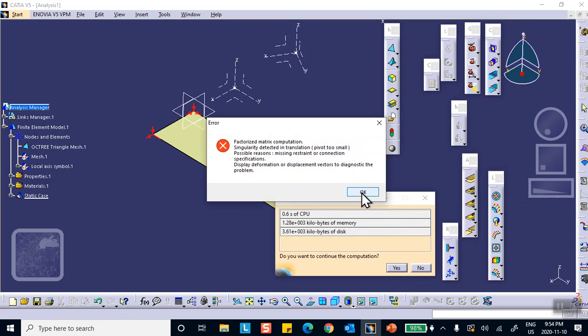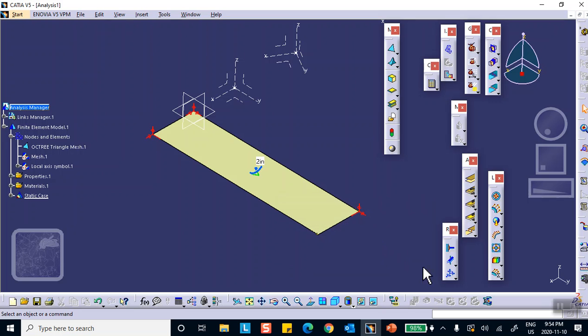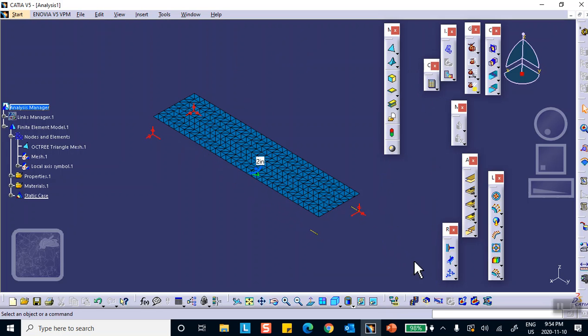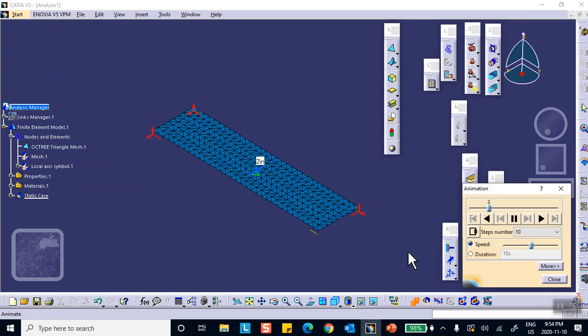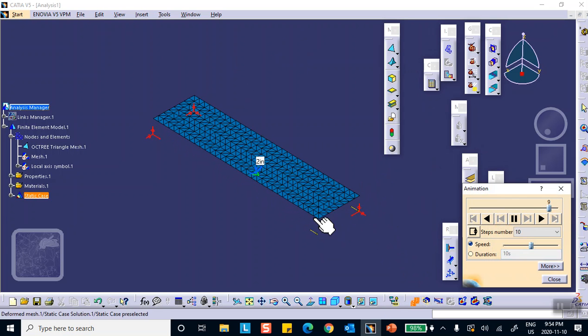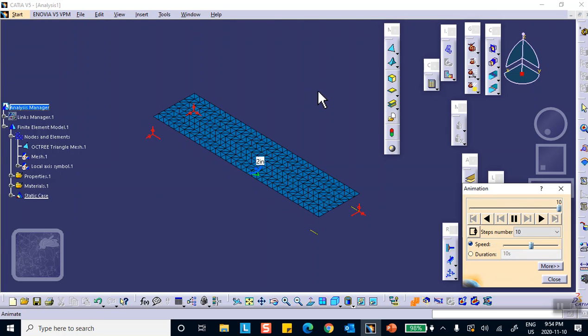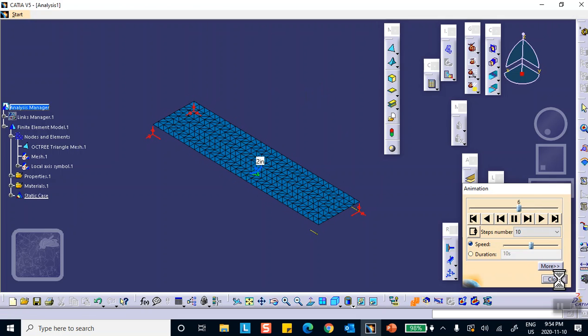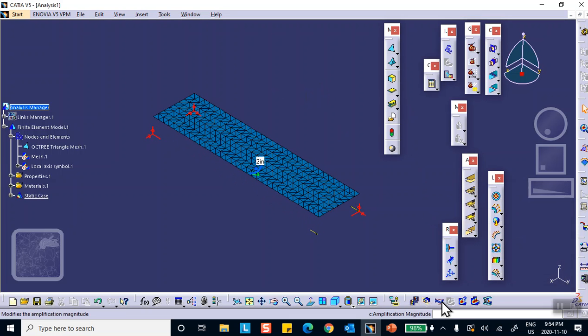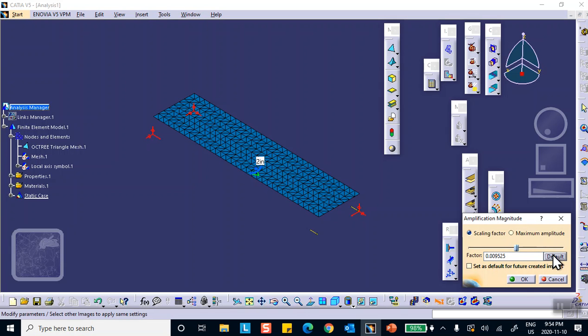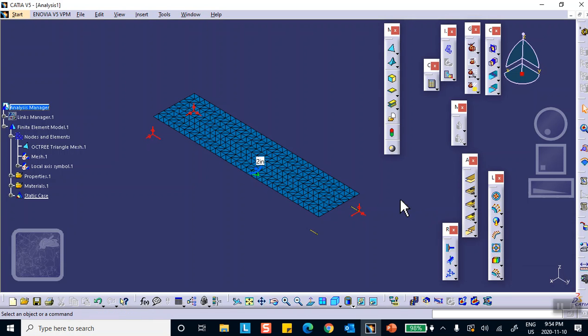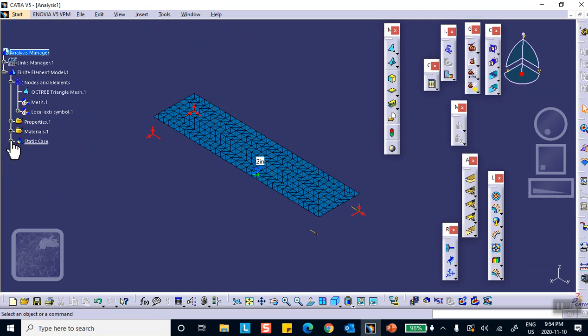There. And the reason, if you want to know what the reason is, you can still plot the displacement or the deformation, and notice that it moves as a rigid body up and down. So what I really need to do is one corner point, I have to prevent it from going in the vertical direction. So let me rewind this and make sure that you reset the scale here. Well, actually, let's go ahead and deactivate this plot. We'll do that later.